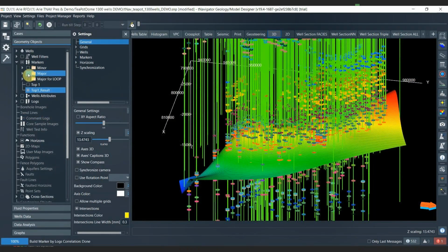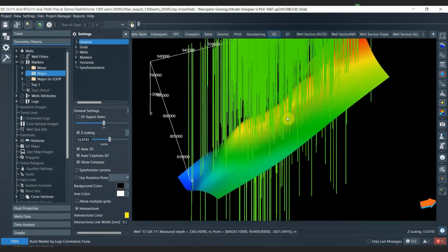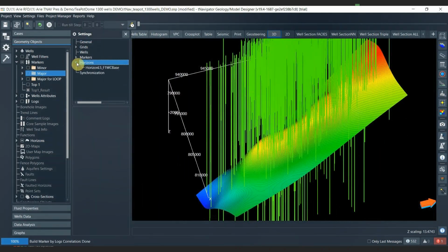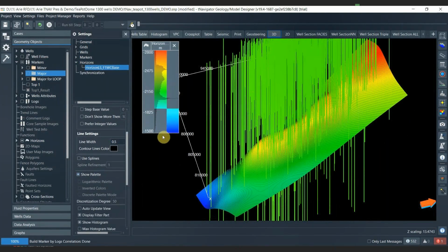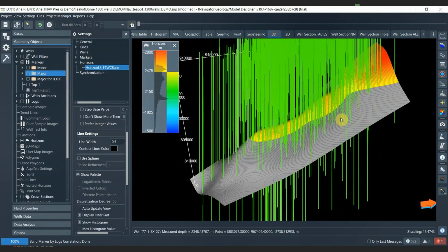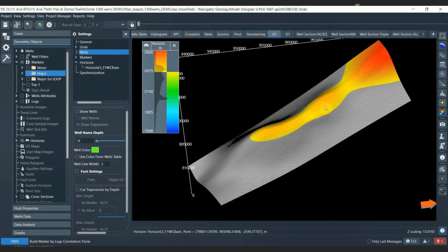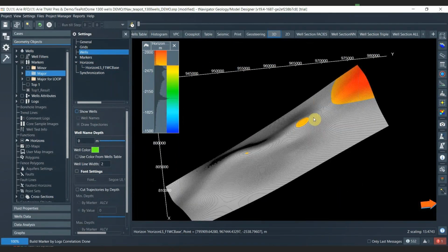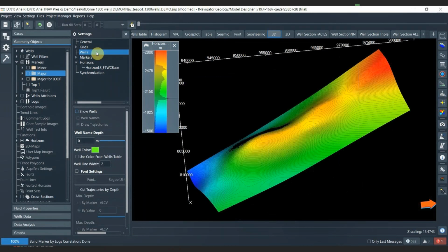And you can also do other things. For instance, you want to do a quick QC on your depth structure map here. You can manipulate the legend. You show the legend, right? And then you can filter out the lower or the deeper depth interval here, right? For instance, like this. So I can see which is my potential oil accumulation just based on the depth structure. It's very light. And then you can see the tree structure here. And if I focus on the higher area, I can show it like that, right? So it's very simple and convenient.